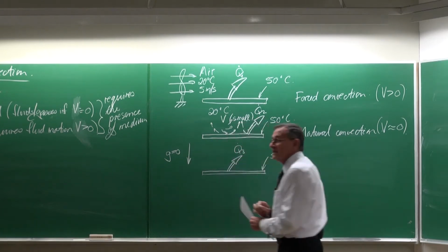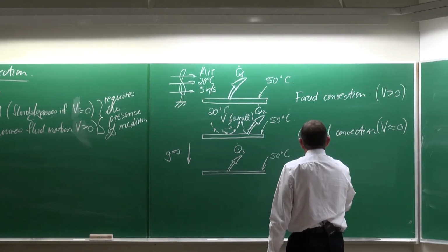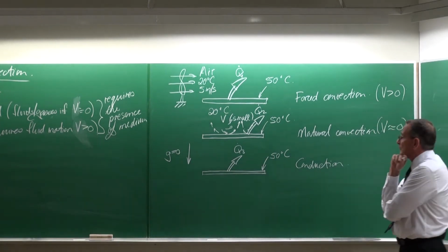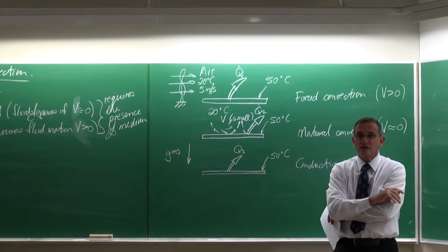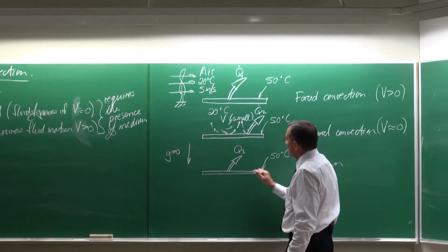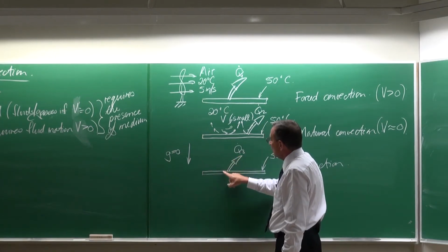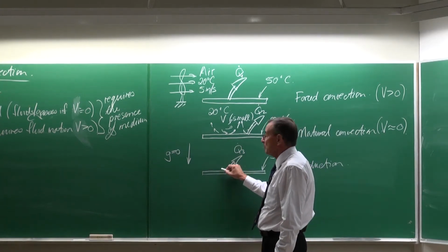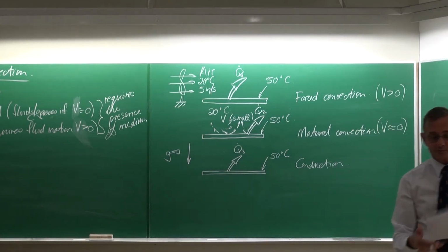There will also be heat transfer, but now the heat transfer would be through conduction. So that is the special case where in a fluid and or a gas, the heat transfer will be conduction, because even although these gas particles or air particles will be heated, they cannot just move up because of the buoyancy forces, because gravity is equal to zero.